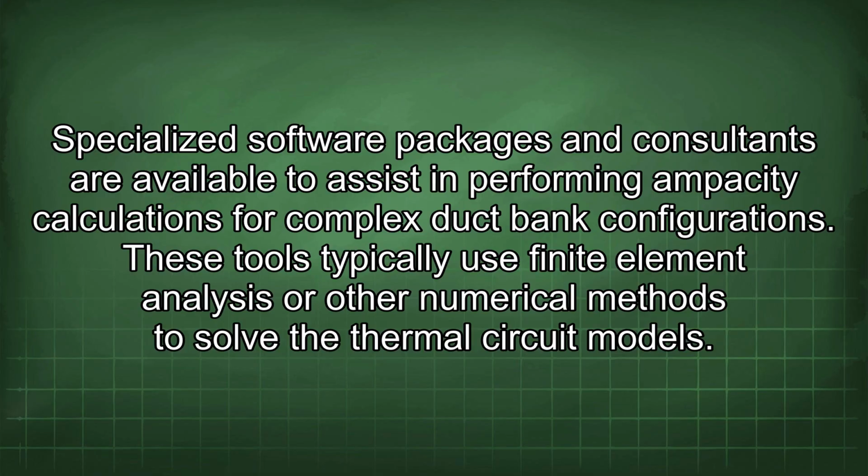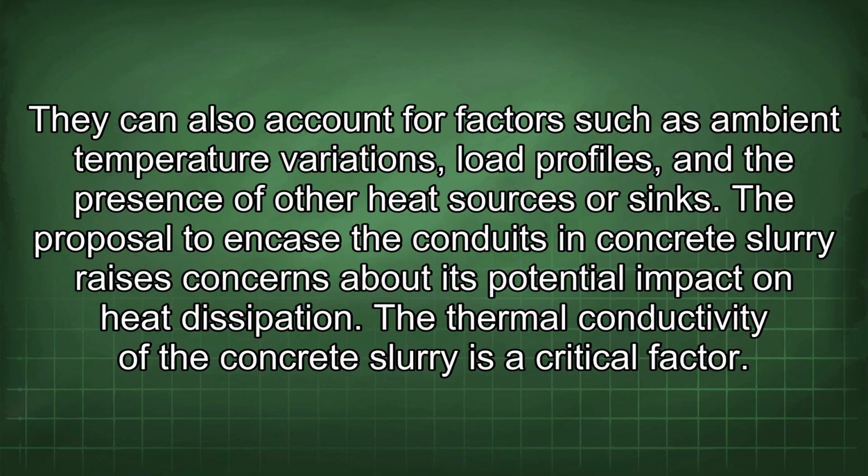Specialized software packages and consultants are available to assist in performing ampacity calculations for complex duct bank configurations. These tools typically use finite element analysis or other numerical methods to solve the thermal circuit models. They can also account for factors such as ambient temperature variations, load profiles, and the presence of other heat sources or sinks.